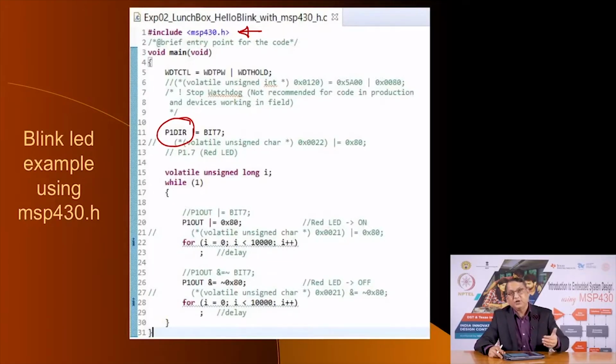But it is possible to access those locations as memory addresses also, because you see MSP430 is a von Neumann architecture, which means the microcontroller or the processor inside has a unified memory map, and in the same memory map you are going to store the program. Some other parts of that same memory map are going to be used to store variables because you have RAM there, and some other locations are port addresses.